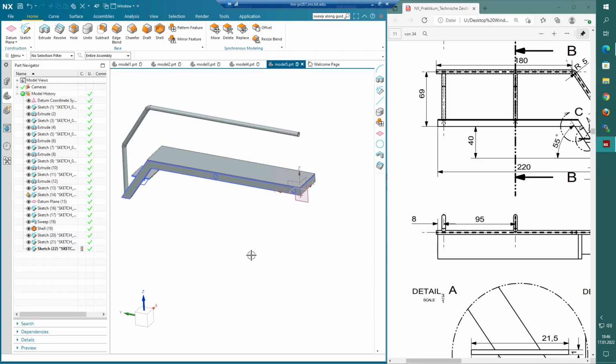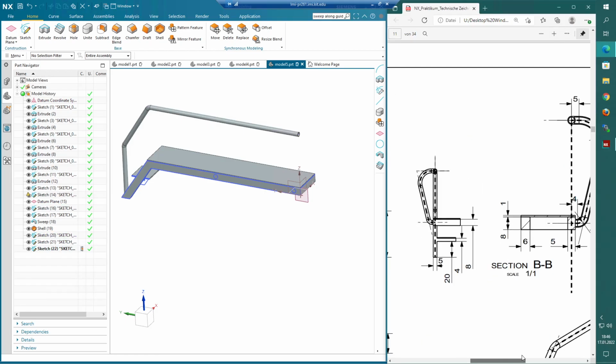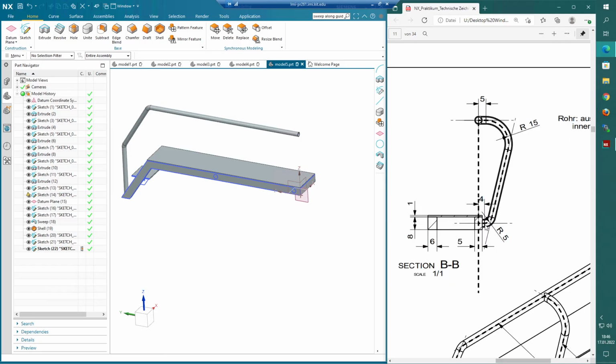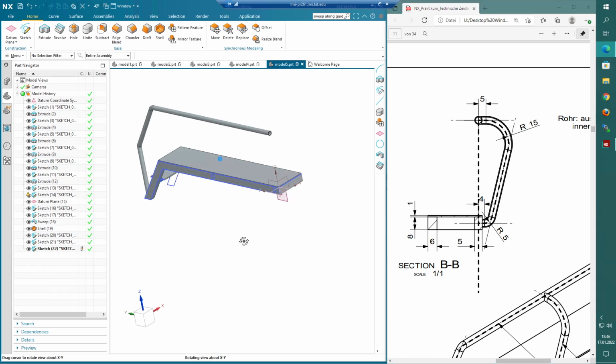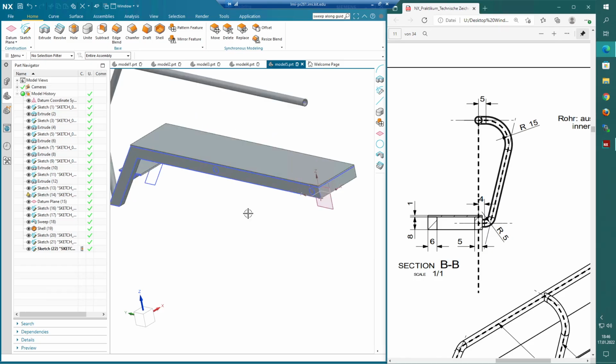Okay, so last but not least, probably last modeling step is now doing the guideline for these 2, and here it comes into play what I explained earlier. You don't need to draw 2 guidelines now because it's not important where the guideline is. It just has to point the right directions, which then are applied to your sketch.